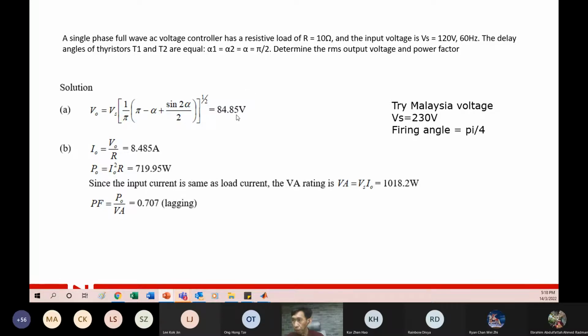Very important is that the output is no longer a sine wave. So obviously two things happen. One is you will have very high harmonics. Second, what comes together with harmonics is the power factor issue. For your load, low power stuff is still okay: resistive load, heating device, magnetic coil, all this is okay.